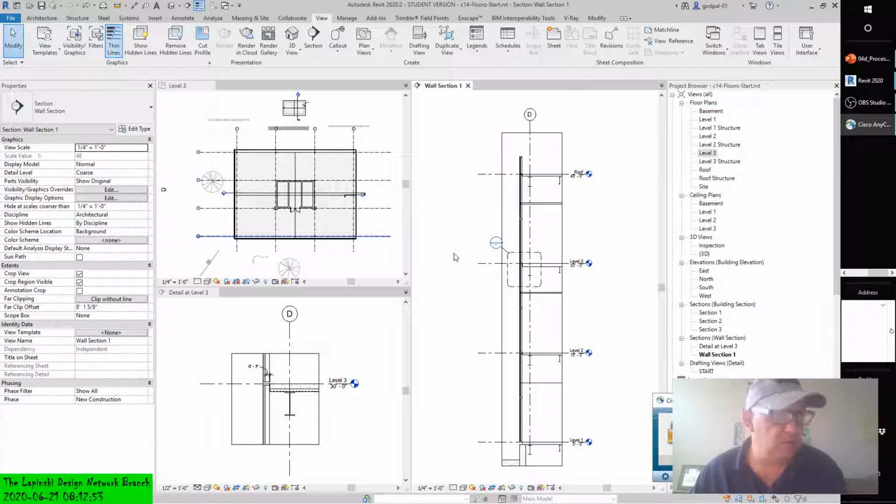Cantilevered metal decking. You can see the metal decking profile shown in a section view. However, when metal deck runs parallel to a support member, the decking cannot cantilever as shown by default when you model a floor. You must customize these slab edges to show a more accurate representation of the decking condition.